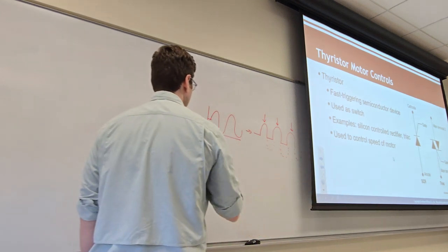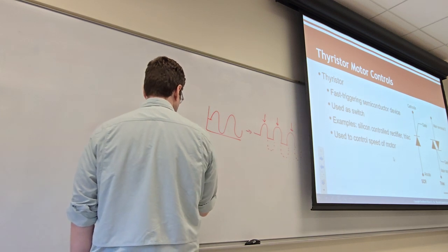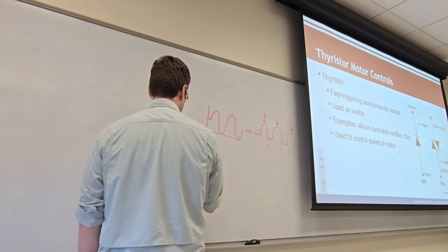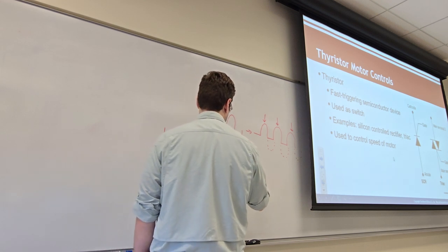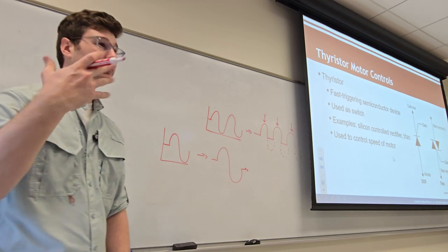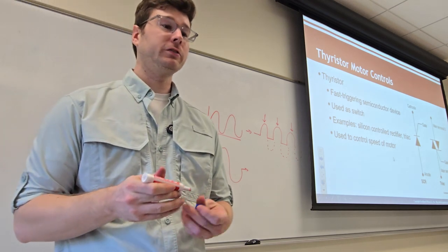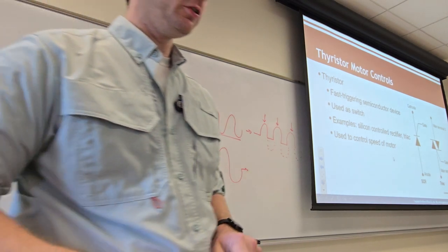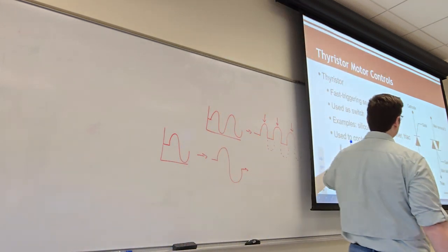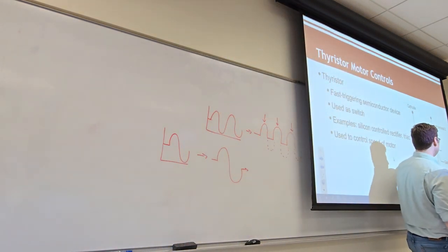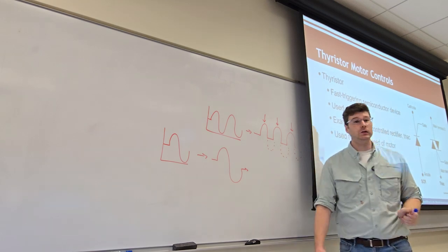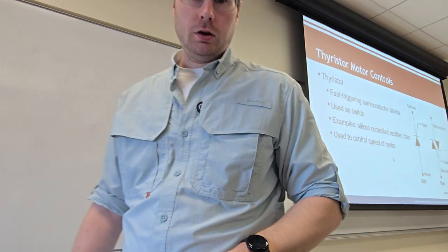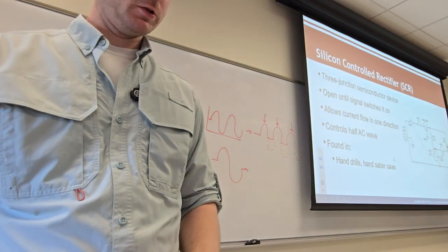Okay. A triac instead passes the full wave. Okay, where as expected, it'll pass the positive and negative lobe, so it'll push and pull the electrons just as we expect it to. Okay, so the difference between an SCR or a thyristor, this is that symbol, and a triac being this symbol, again, it's more like a transistor for AC, is that it will pass both bumps of the signal. Okay.